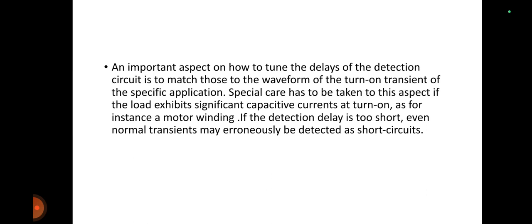The approach on how to tune the delays of the detection circuit is to match those to the waveform and turn on transient of the specific application. Special care has to be taken with this aspect if the load exhibits significant capacitive currents at turn on, for instance a motor winding. If the detection delay is too short, even normal transients may erroneously be detected as short circuits.